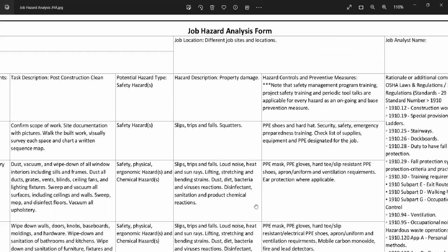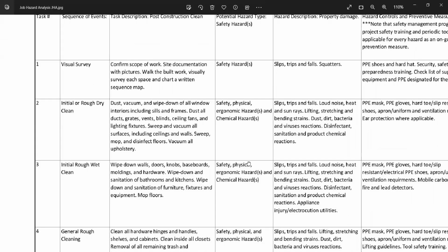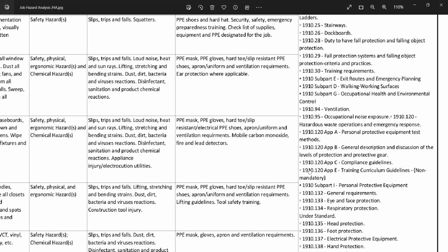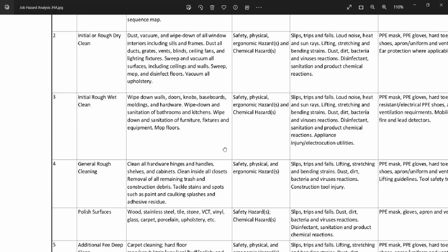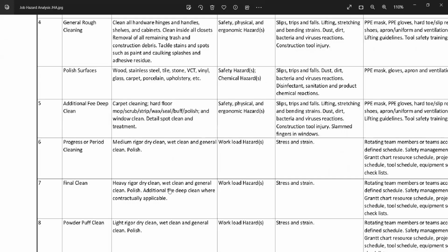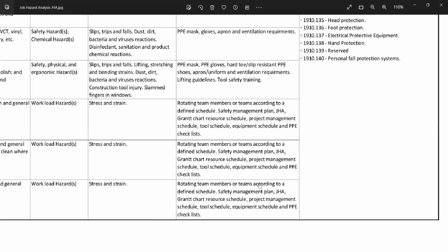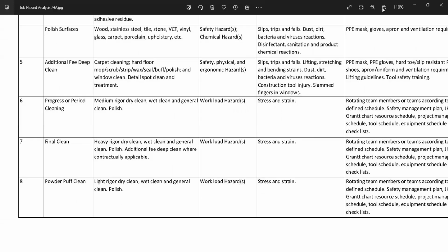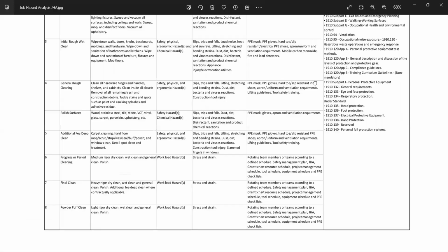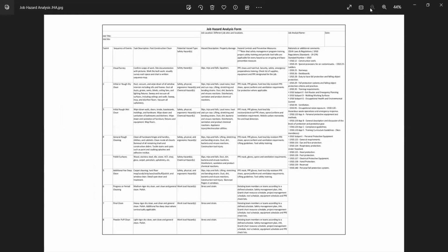Stairs and stairways. Are standard stair rails or handrails on all stairways having 4 or more risers? Exiting or egress. Are all exits marked with an exit sign and illuminated by a reliable light source? Are doors that are required to serve as exits designed and constructed so that the way of exit travel is obvious and direct? Any elevated surfaces? Are signs posted showing the location of the elevated surface? Hand tools and equipment. Are all tools and equipment in good condition? Are hand tools reconditioned or replaced as necessary?